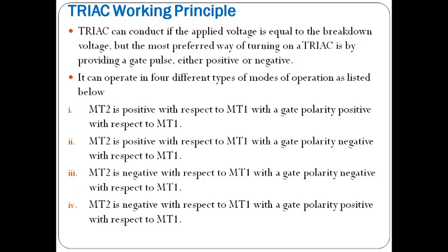Yes. So triac can conduct if the voltage is equal to the breakdown voltage, but the most preferred way of turning on triac is providing a gate pulse, either a positive or negative pulse. So in silicon control rectifier, SCR will turn on if the voltage applied is greater than the breakdown voltage.